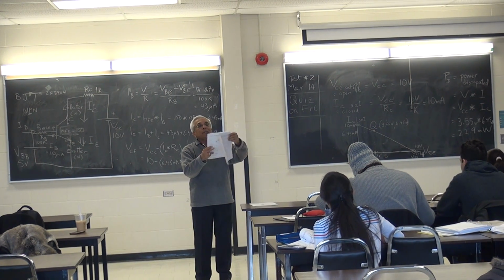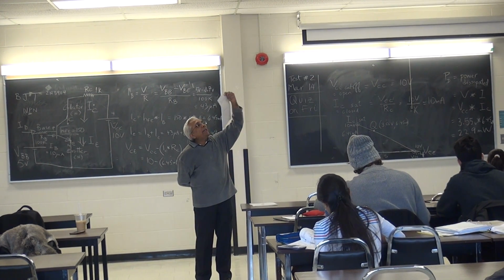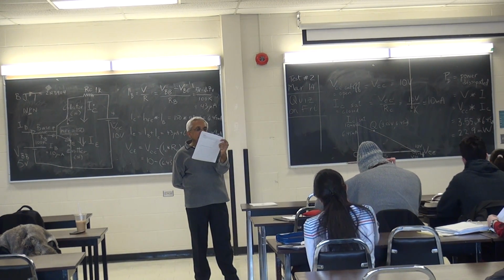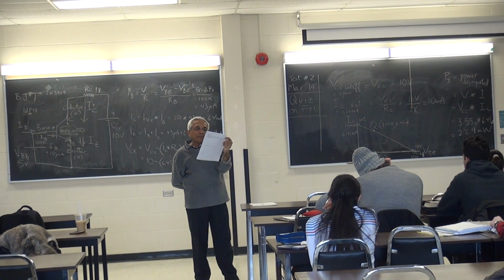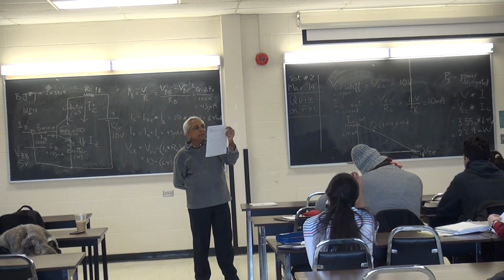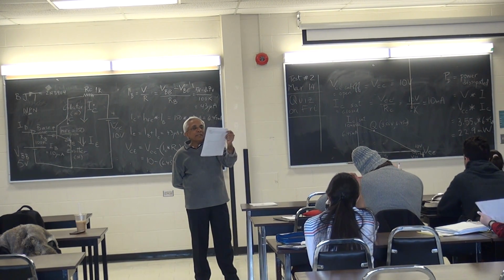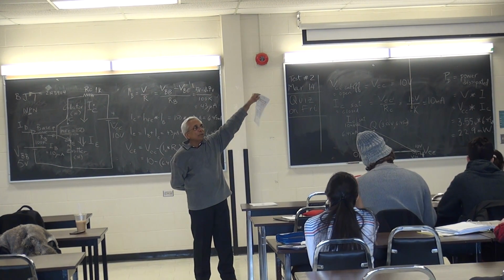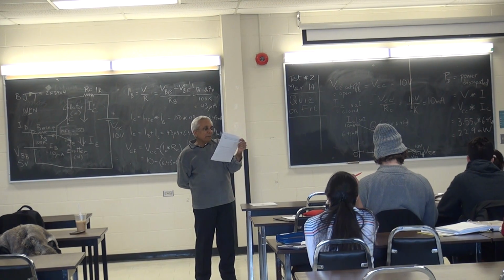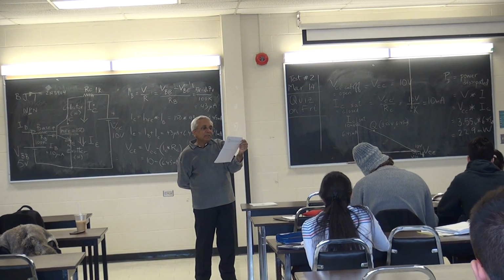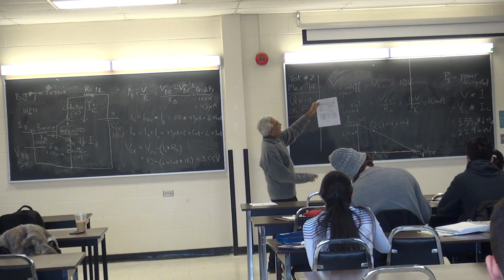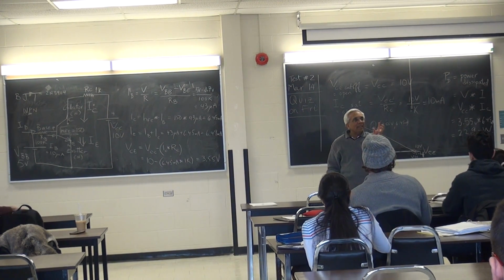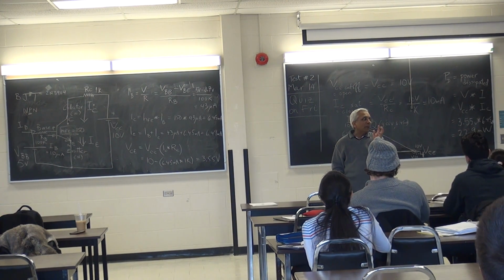So, go to the appendix. Go to page 13. On page 13, we have the value of power in the table. P total, total power dissipation. For this model of transistor, the 3904, what is the power dissipation maximum? 500 milliwatts. If I had a transistor like this in this circuit, it can handle 500 milliwatts of power.